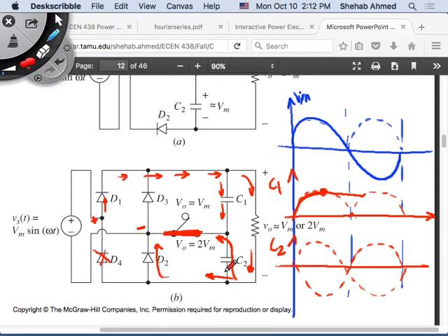So current will see, okay, what opposes current? Impedance and voltage, right? The capacitor is discharged, so there's no voltage to oppose. There's just the impedance of the capacitor. So it's a short circuit. So there's no voltage, so current can flow here, right? But what do you mean it's a short circuit? It has no voltage. But XC is 1 over omega C.